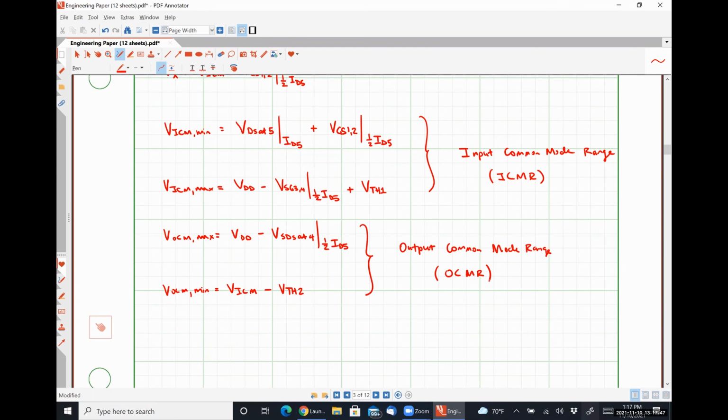So effectively you get a really high gain, but you're crunching your input common mode range and your output common mode range on the DC side to get a very, very large low frequency gain for small signals. Or we could revisit the frequency response of these and talk about compensation, which is how you connect the second stage to make one of these actually able to drive something other than a capacitor. So which option do you want to talk about?